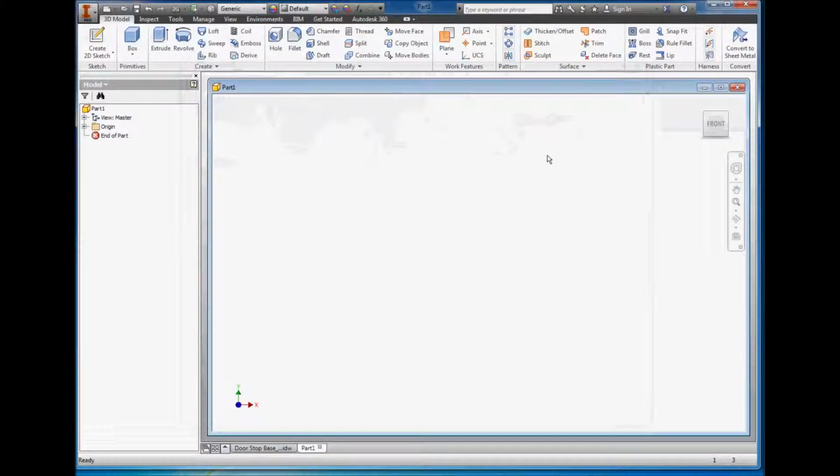Once we get started, this is our workspace. This is the feature tree. It works similarly to, if you guys have used Photoshop or Illustrator, the history toolbar. It logs every single sketch and feature that you do. And the cool thing about it is that you can go back in time to a feature or a sketch that you've done. You can edit that sketch and then update the model. Everything from that point onwards updates to reflect the changes you've made in the past. I'll go through that in a bit more detail when we get around to that.